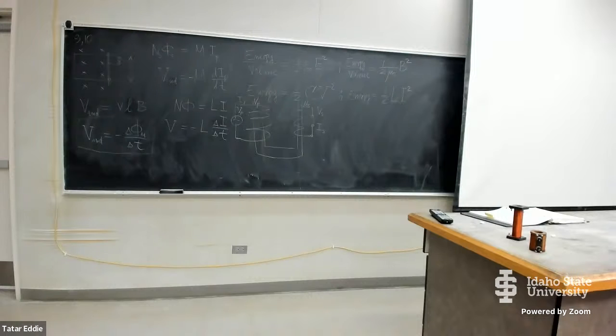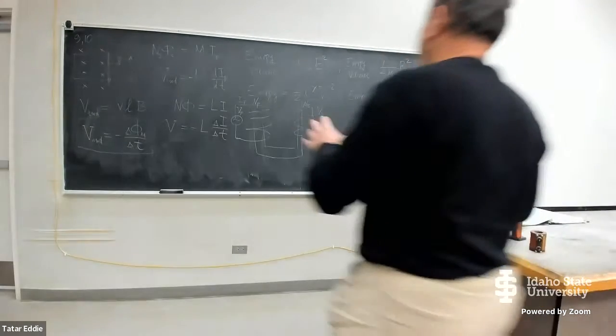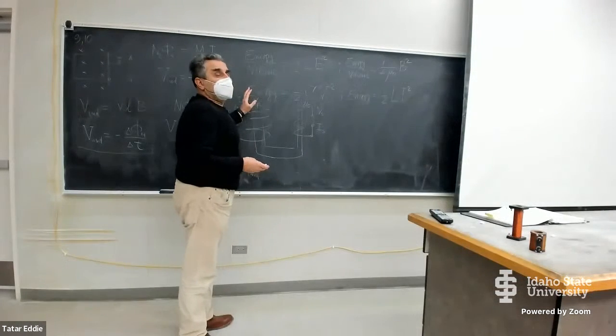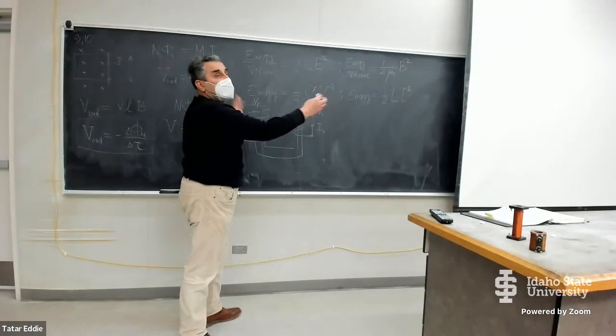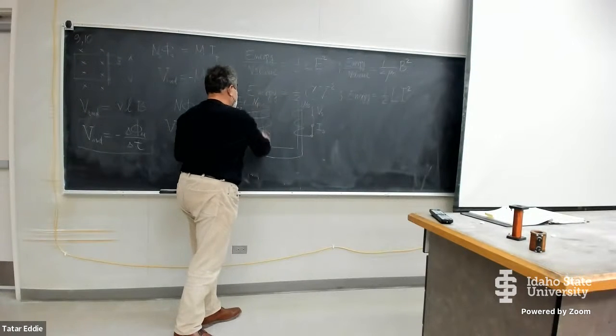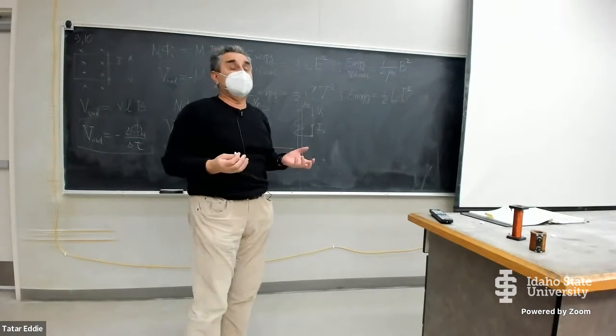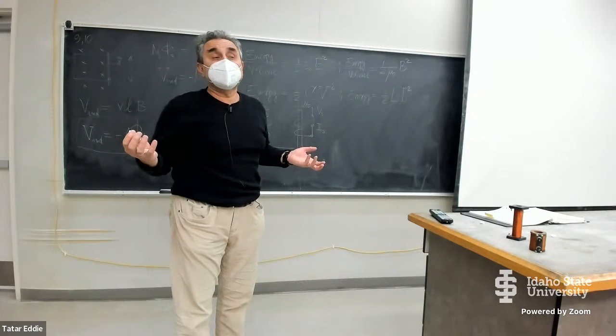It is quite heavy, but you have the primary coil right here, the secondary coil here, and they are connected with this solid iron connection. No electrical connection. The iron core is just to drive the magnetic flux. The magnetic flux shouldn't stray in space. The magnetic flux has the property that it prefers to go through iron or other ferromagnetic material.